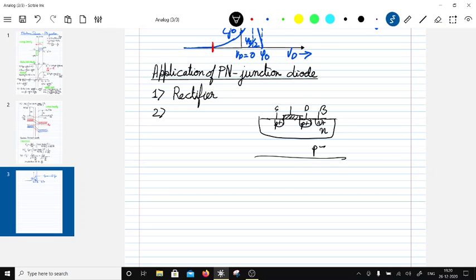The P substrate is connected to the most negative potential, which is going to be 0 or ground. So this junction is going to be reverse biased. This causes the device to be isolated from the bulk. Even in the case of NMOS in an N well process, there is a depletion region because of the reverse bias, and this depletion region isolates the device from the bulk.